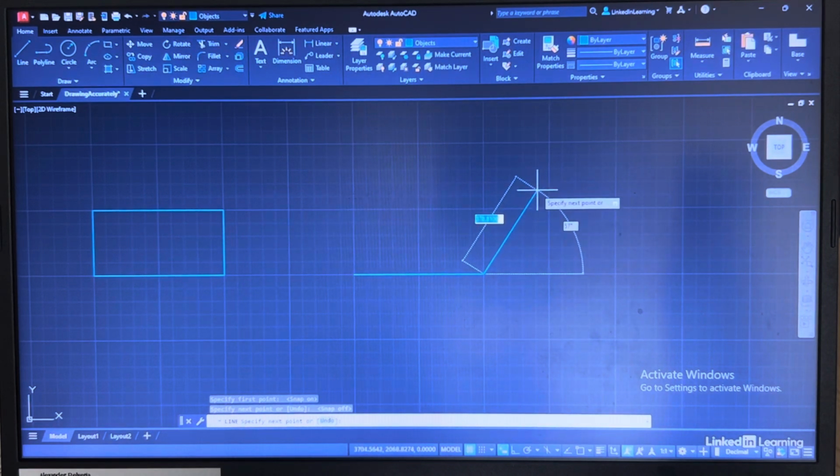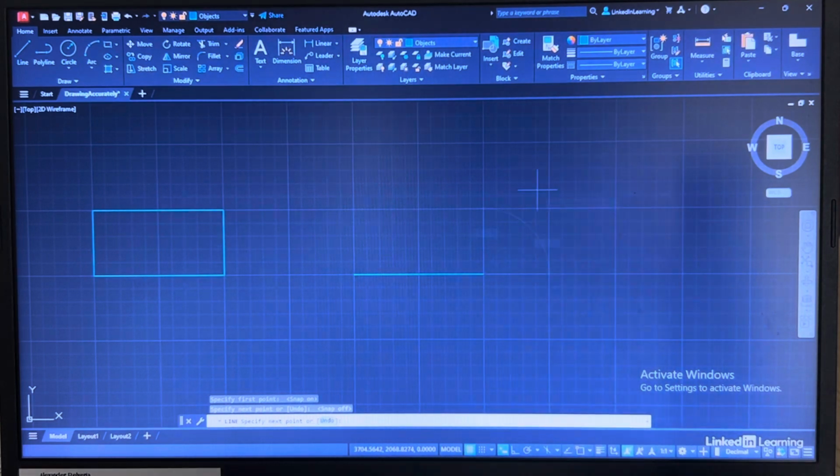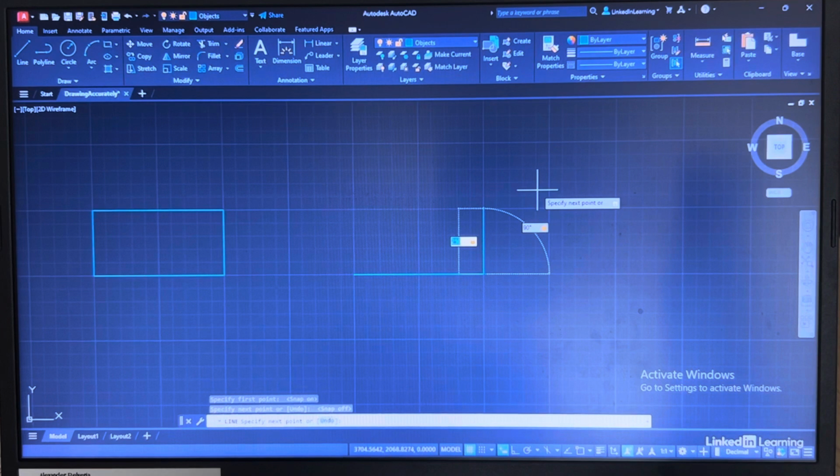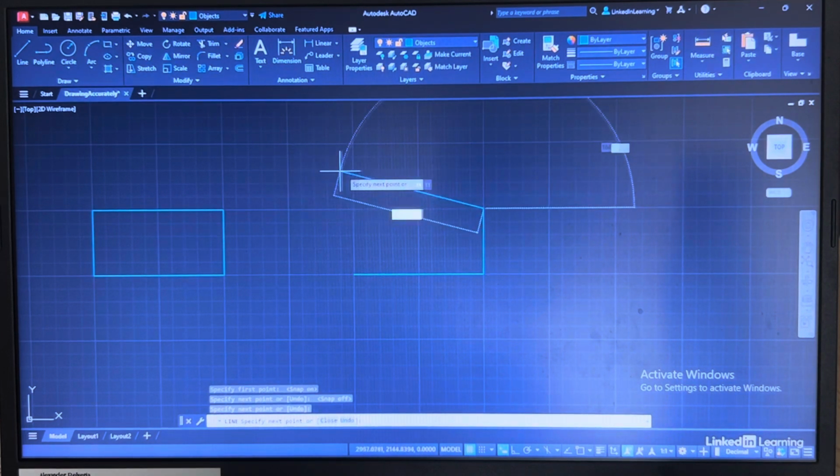So now I type in 250, press tab, and I want to go vertically upwards, so that'll be 90 degrees based on the east is 0 unit setting that we talked about with the direction, remember previously. Tab again, and there's our vertical segment. Just left click on the mouse to confirm, and then it prompts you for the next part of the line. So I'm going to come this way now.